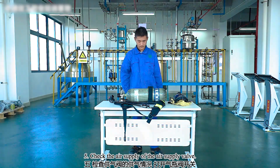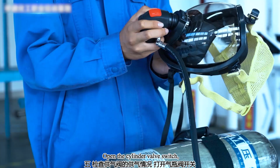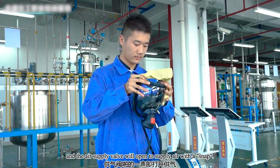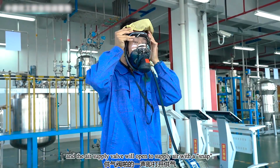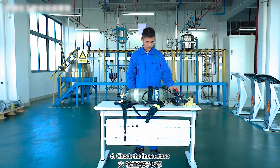Fifth, check the air supply of the air supply valve. Open the cylinder valve switch. Wear the mask air supply valve, take a deep breath, and the air supply valve will open to supply air with a snap. Sixth, check the intact state.